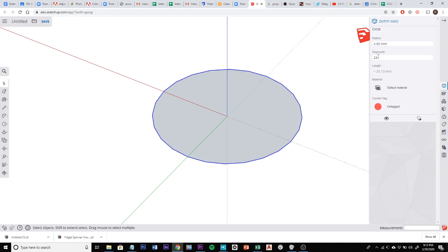Now I could increase that if I wanted my circle to look smoother and not have visible facets. So I'd increase this to, let's say, 150. Well, let's do 360. That'd be a lot of segments. That's actually too many segments. Because I'm working with a small object, it's not going to make the segments smaller. There's probably a limit to how small they can get. So let me try something like 100. That didn't change either. So let's try 48, twice as many. There we go, that worked.